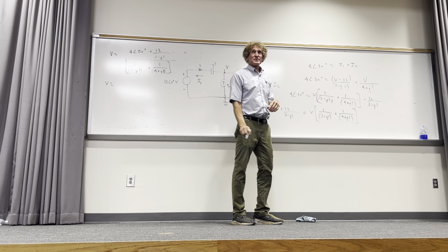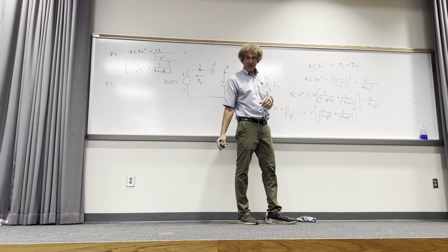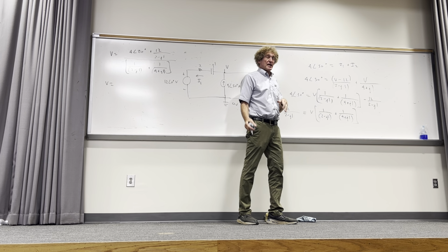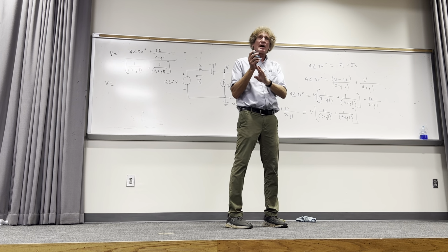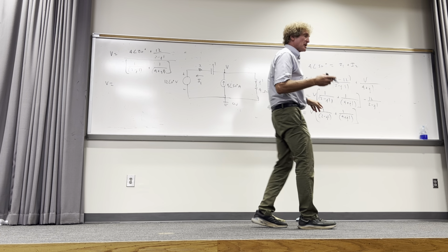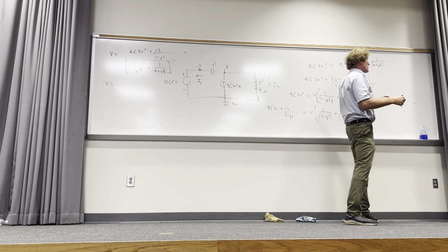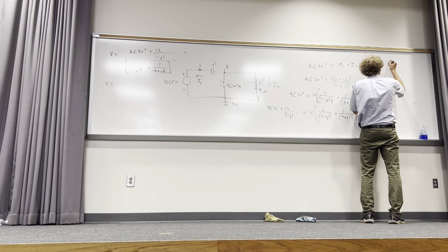A lot of times, when you're looking at something like this, these numbers bother you. You know, they do. So one thing, and it depends, your calculators, I think, can just allow you to enter complex numbers. I don't think it's very difficult to do that. Maybe a little tedious until you get used to it. But if you have something like this, 1 over A plus JB, and you don't like that 1 over business, then you just want a real and imaginary part, you can multiply the top and bottom of this by A minus JB.